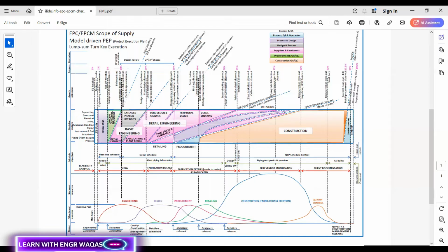It is used to verify that the installed piping conforms to the project specifications, standards, and codes before commissioning. There can be different kinds of tests like MPI, UT, visual. This ensures quality and helps avoid incidents and mishaps.